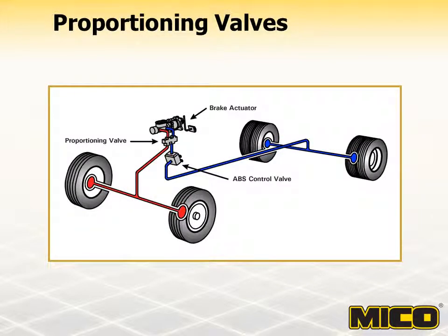After this pressure is reached, force to the rear brake lines is allowed to rise at a portion of the maximum available. The valve does absolutely nothing during normal or low-pressure stops. A variation of this valve is the load-sensing proportioning valve. It is found on some four-wheel drive sport utility vehicles and various small trucks. The distance between the body and the axle changes as the rear springs compress under a load. This distance is used to adjust rear stopping power to match the weight on the rear wheels and prevent lockup.